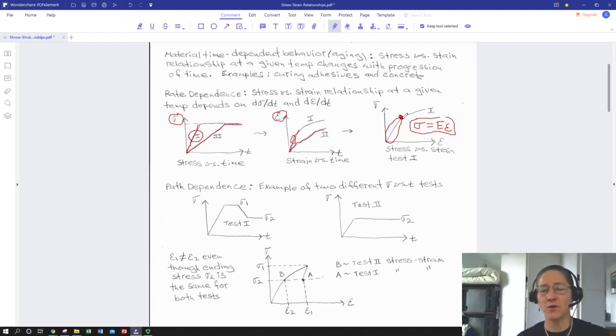If you deform the material past this yield point, or if you apply more stress than would correspond to stress yield, then you actually start invoking new mechanisms of deformation. You'll actually move atoms to a new stable position. This is known as a mechanism called dislocation movement in metals, microfracture advancement in ceramics, chain slippage in thermoplastics. But in any case, it's moved, it's in a new stable position, and if you let go of the material, it's not going to go back to the way it was.